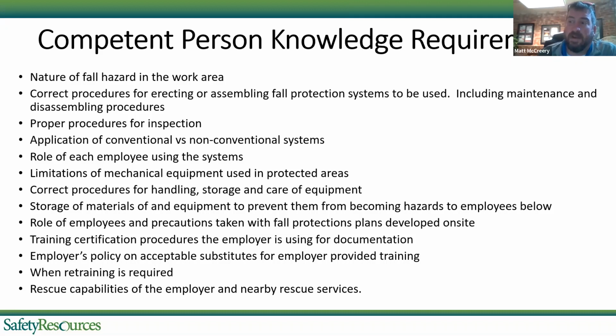And then we're going to actually talk about rescue as well, because that's something I think people forget is required in the fall protection standard. If you have a steep slope project, let's use that 200 foot in the air hospital I was talking about, you better have a rescue plan for those folks. There's a variety of ways you can put that together, but I'll show you how we sometimes do it for some of the smaller projects towards the end of the presentation.